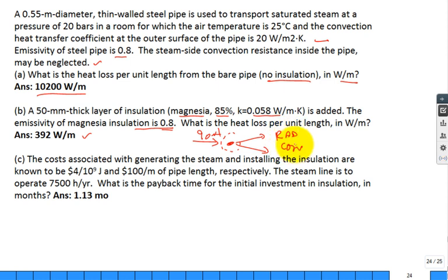So we want an energy balance for a thin surface on the outside of that insulation. Okay, you have flow coming through the insulation. So that Q conduction would be the K times a delta T, let's say T interior minus the T surface. I'm going to solve for the surface temperature.